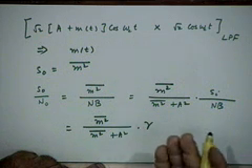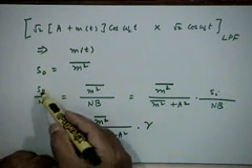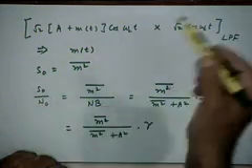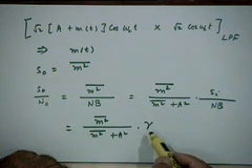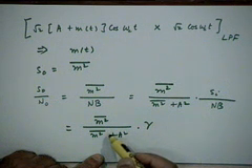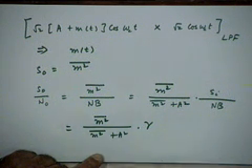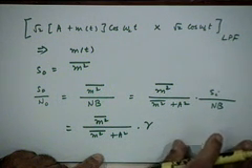So therefore you lose in terms of performance. That is, to get the same SNR as the other systems, you will have to have a higher value of gamma because of this attenuation factor that is coming into the process. Is that okay? So obviously in terms of SNR performance, AM with carrier would be inferior. Have you all understood this?